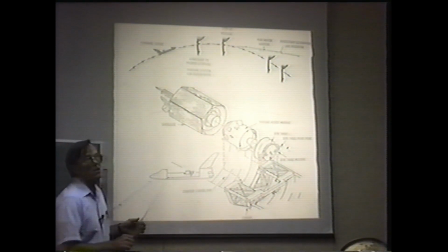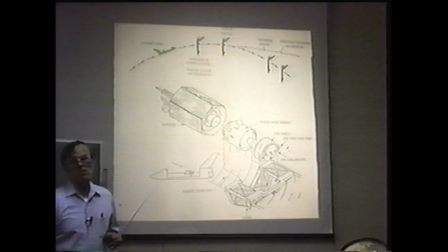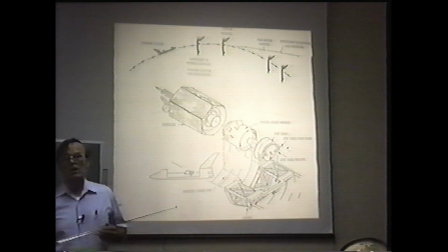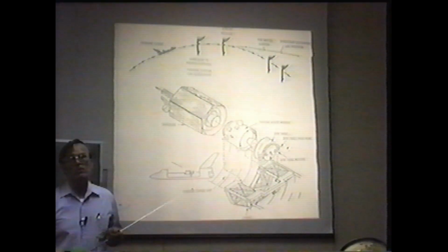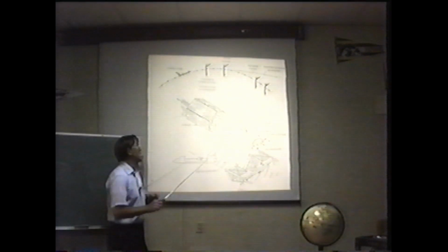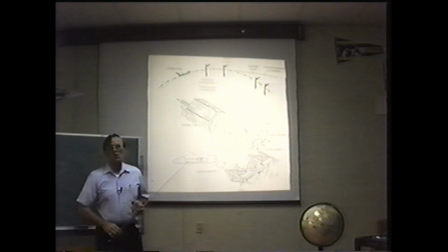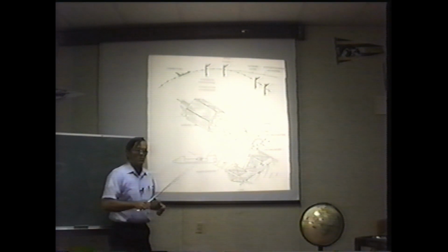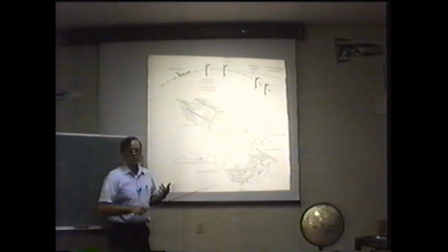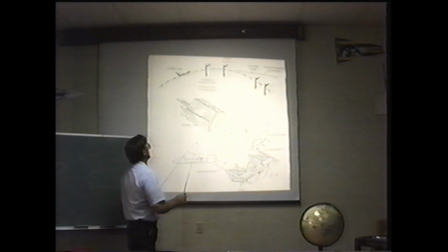So it rotates, thereby allowing exposure to all of the solar cells so that you can collect power all the way through. Also, while you're orbiting in space, you pick up dust particles and other things collide with the satellite, and if you didn't spin, certain cells on the solar array would become damaged and no longer effectively collect the power for you to use in the satellite. So at any rate, by spinning, you are able to use all of the cells, and that way when you lose 10 or 15% of your cells due to damage, well then it will continue functioning.